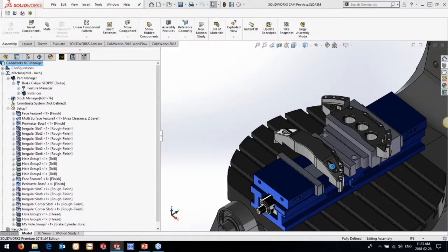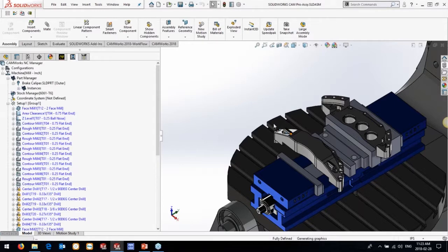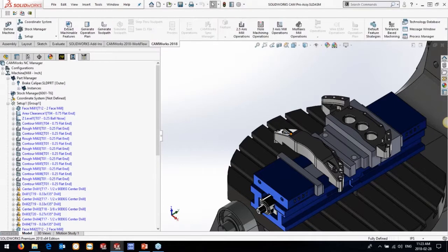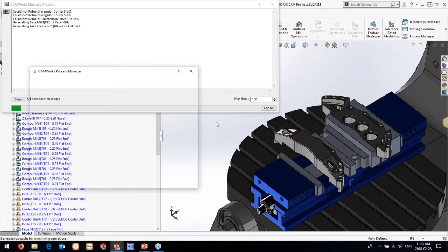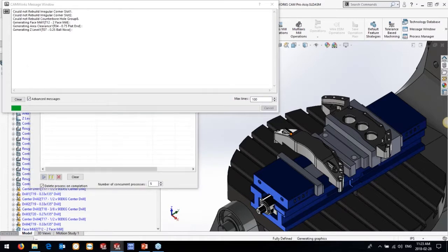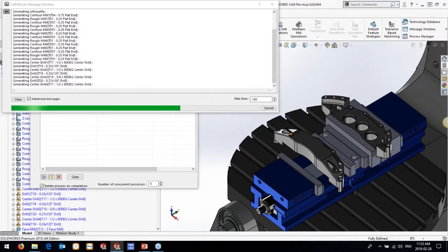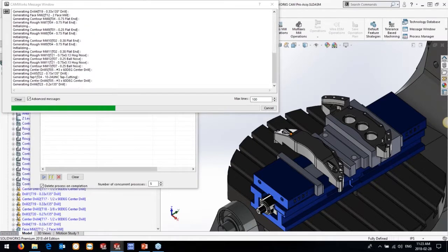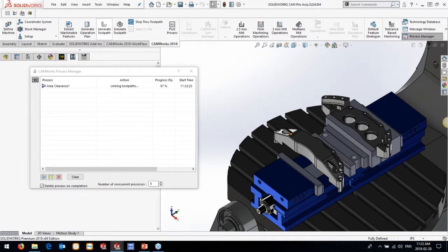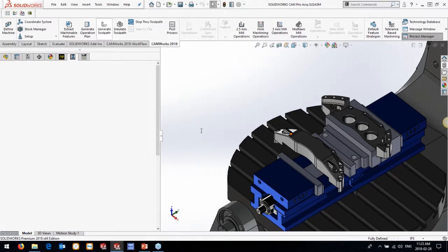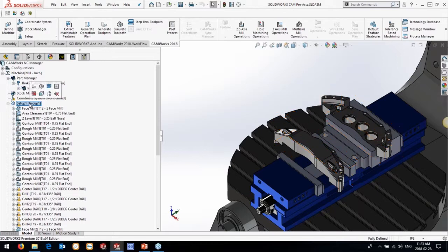We've got some holes that are coming in the side here for the brake lines and the hydraulic fluid. Basically, those need to be indexed, so we can calculate the new positions to index the table to get them into the correct orientation. And all we have to do is regenerate the toolpath, and we've got essentially our program imported from the part file into a model. And in this case, this is a 5-axis machine, so we're tilting everything around.